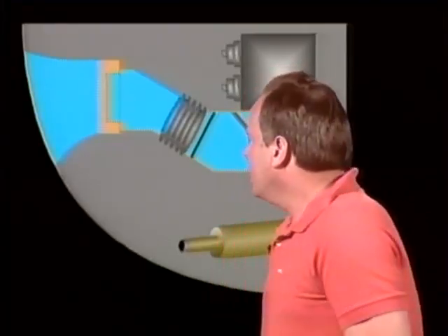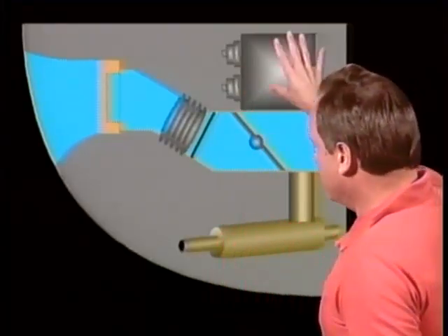Now, sometimes, if you want to increase the vaporization, make sure that the fuel-air mixture is totally vaporized, you can increase vaporization by circulating the fuel and air mixture through passages in the oil sump on the way to the cylinders themselves. So on small aircraft engines, you need to know fuel vaporization may be increased, and I'm giving you FAA magic words here, by circulating the fuel and air mixture through passages in the oil sump.